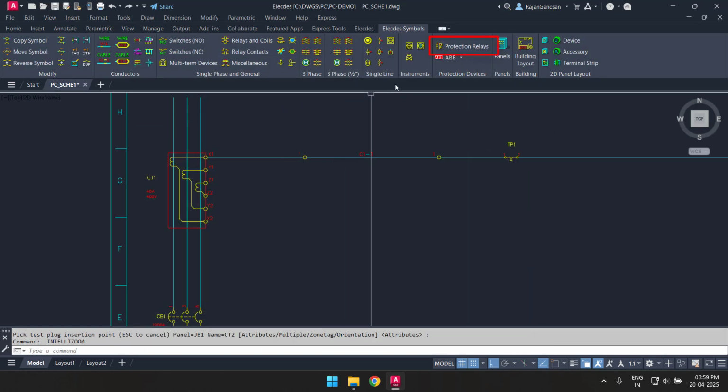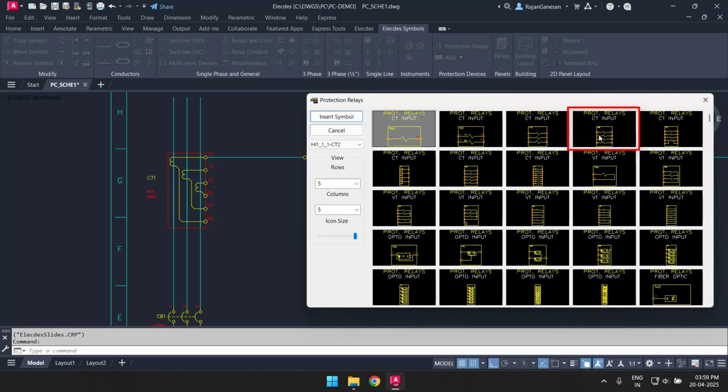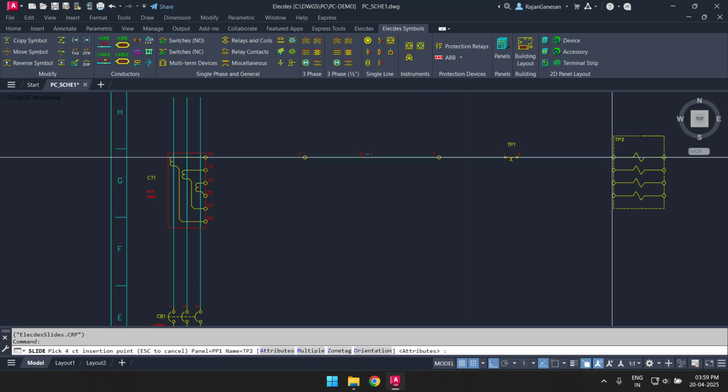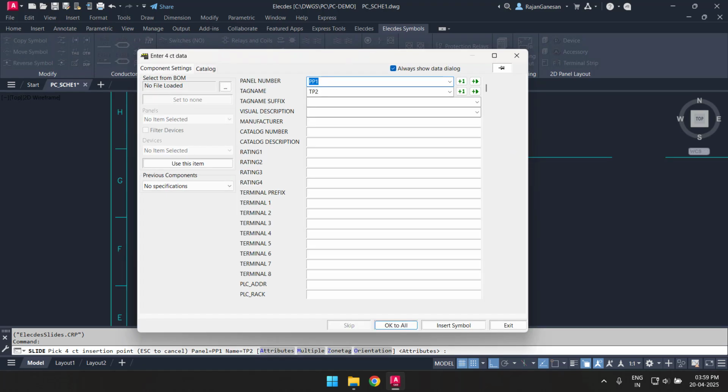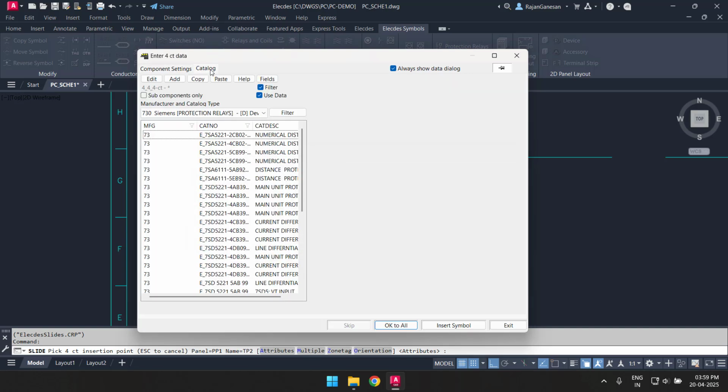I'll now use the Protection Control component menu to insert a CP input block. I can drag the block onto the conductor and then drop it. I'll name my relay R1. I'm going to use a Schweitzer relay from the SEL315 family. This relay is complex and specifically for managing large circuit breakers.